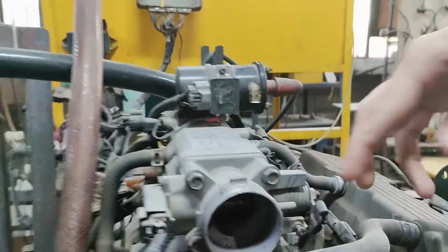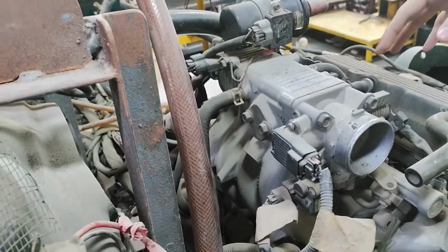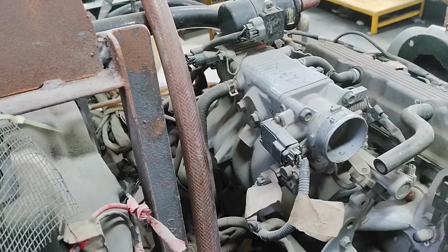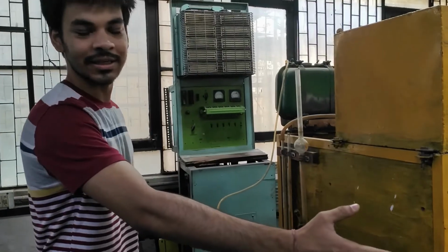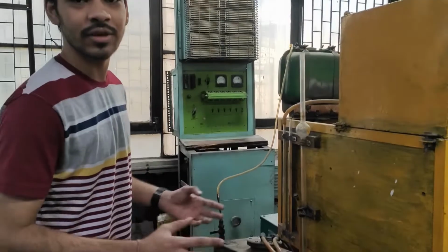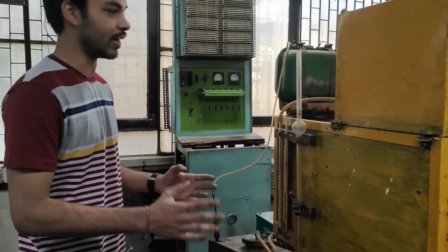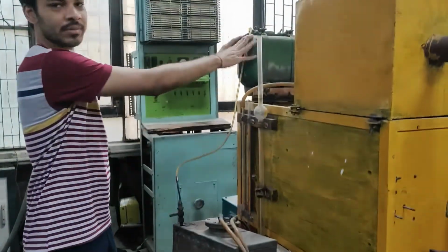The amount of air which is flowing inside goes into the manifold, and there are sensors present inside this entire engine system which calculate the amount of air which is coming in. The data from these sensors comes into the ECU, and the ECU calculates the optimal air-fuel ratio which is required. The air-fuel ratio is obtained when the fuel pump takes the fuel from the fuel tank into the fuel rail and fuel manifold which is present.